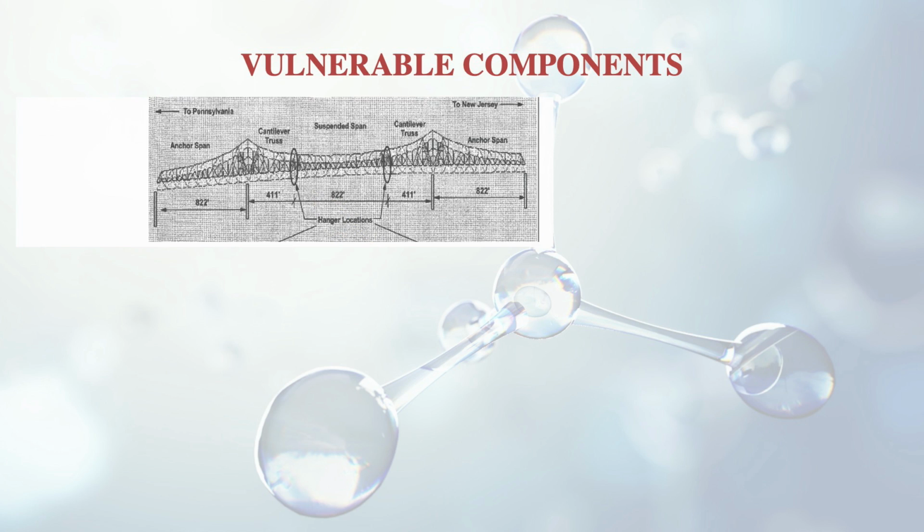So this is very common. A lot of bridges in the middle of the previous century were constructed with this kind of arrangement. Here there are 4 hanger pins which are connecting the suspended span with the cantilever span. So these hanger pins are very critical in nature.